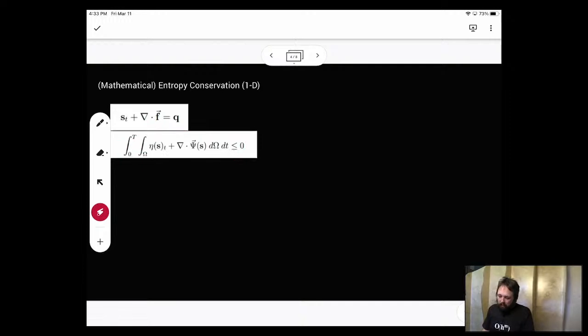So let's think for a minute, though, about 1D shallow water equations. Again, I'll put these guys back up here. I have dh/dt plus (hu)_x is 0. I've got hu_t for the momentum equation. And I'm going to write it in a slightly different form because it's a little bit easier to work with when we're talking about entropy conservation.